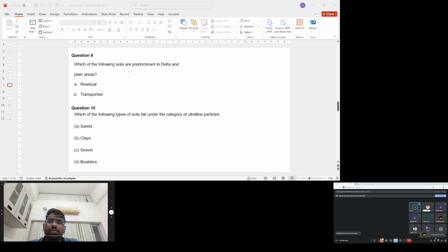In some applications we may not prefer poorly graded sands; we need a blended material, for compaction we need a blended material. So the answer cannot be objective. We cannot say outrightly that we prefer residual or transported, and we should also consider the type of soil based on mineralogy, and several other aspects before using a particular soil for a particular application.